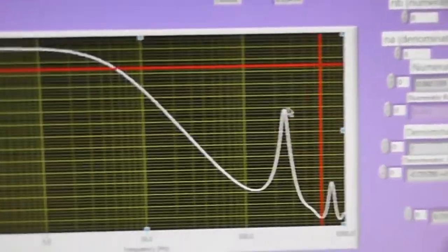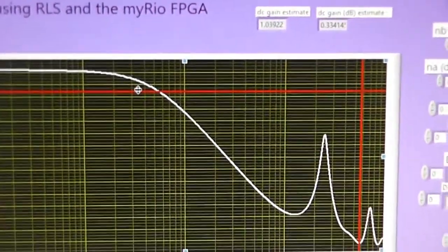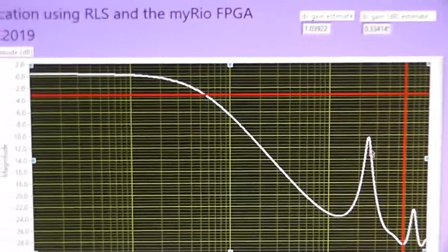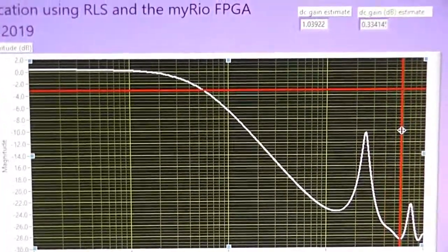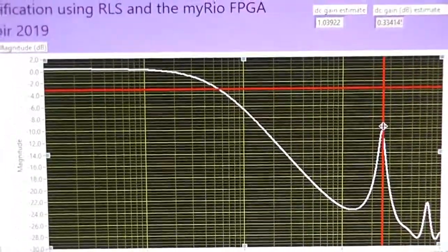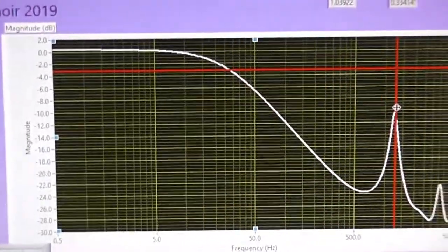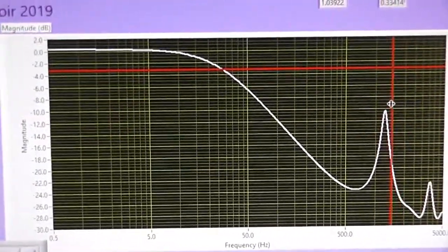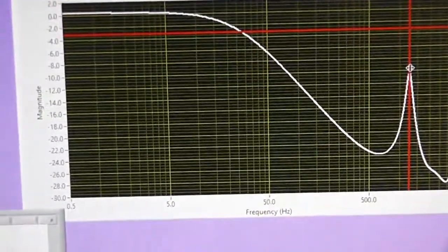And this is the thing that gives you trouble, this resonance, when you try and operate at a very high bandwidth. If you're running at very low bandwidth, you never see this at all. I mean, a lot of control systems textbooks never even mention it because they're just doing very simple things really and running at a few hertz bandwidth, and it's not really what you want to do. You want to try and make the thing respond very quickly. So we can see that this would limit our frequency response.